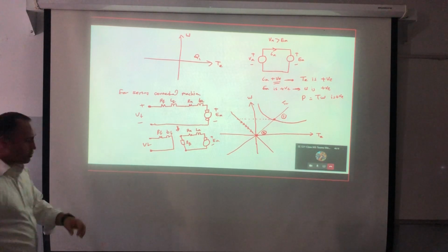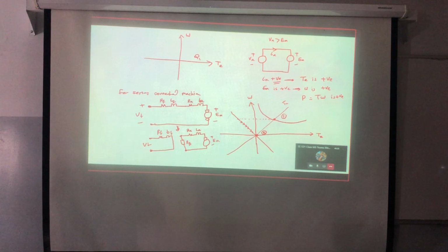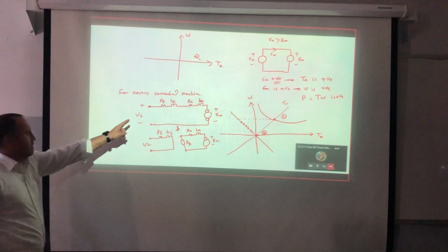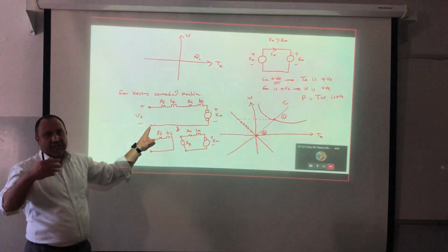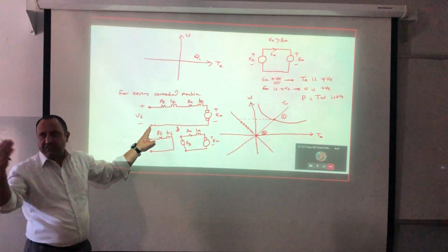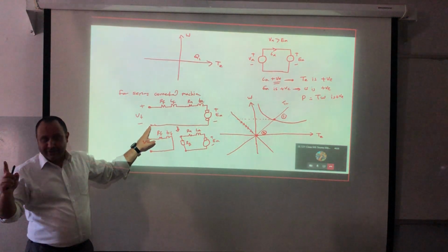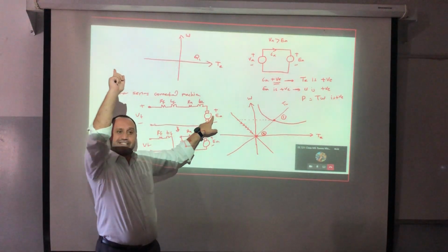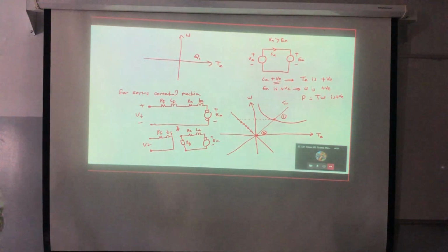So I made it here like a shunt. Yes, otherwise I cannot do the dynamic braking. Because if I did the dynamic braking here, someone would say, okay, the current will start reducing, but the flux will start to reduce, so omega will increase. Good? What about the shunt, the same thing, we must convert it to separately excited? No, we must convert from shunt to series. The same thing, I should keep the flux constant.